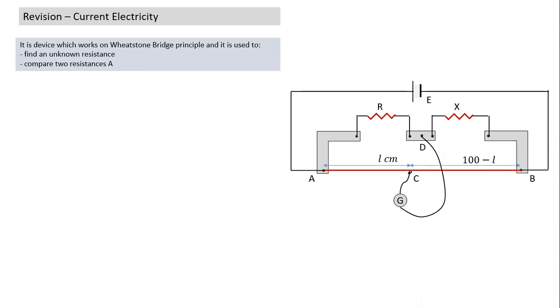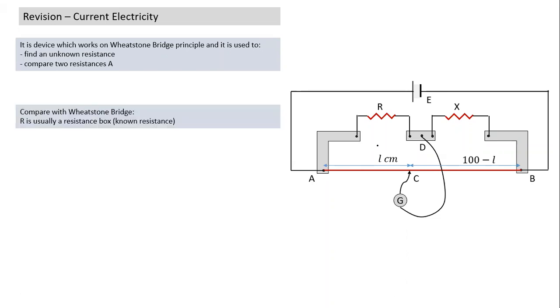And here, this is something like a jockey, which you can slide on the meter bridge wire, and the jockey is connected through a galvanometer, and this is a kind of circuit here. So this also is a Wheatstone bridge. Across one diagonal we connect a galvanometer. Across the other diagonal we connect a battery. That's a Wheatstone bridge. And in the balanced state, when the current through the galvanometer is 0, the ratios of resistances are equal. That's in the case of the meter bridge.